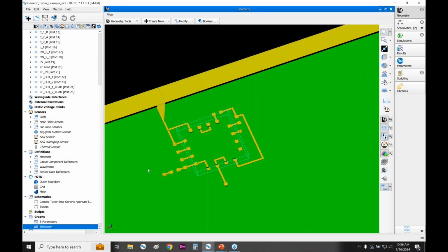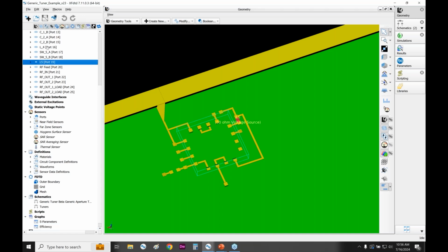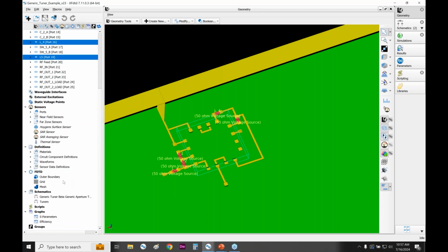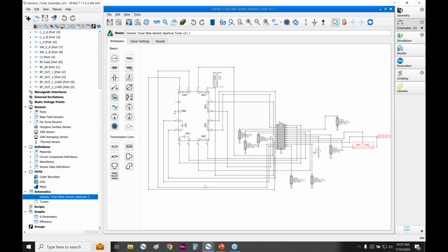We have the impedance tuner, where there's a tune code that controls the switch states and the capacitor values within the impedance tuner itself. And then separately, there are the fixed components outside of the impedance tuner, and you need to determine those values as well. And so the question is whether or not we can optimize that concurrently, and the answer is yes.